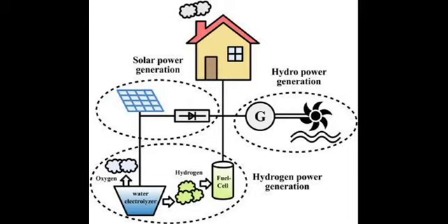Energy needs assessment. Analyze the energy demand in the target location. Consider current and future energy needs, including seasonal variations and trends. Identify the types of energy required (electricity, heating, cooling) and their respective load profiles, which are patterns of energy consumption over time. System sizing. Based on the resource evaluation and energy needs, size the renewable energy system to match the demand appropriately. Oversizing or undersizing the system can lead to inefficiencies and increased costs.